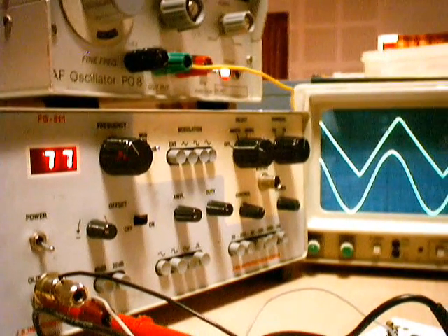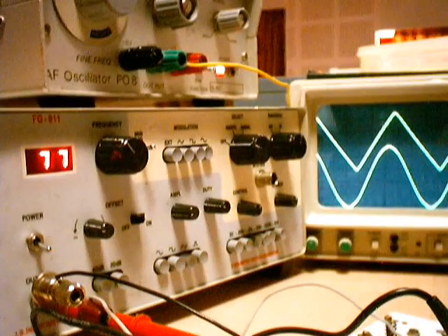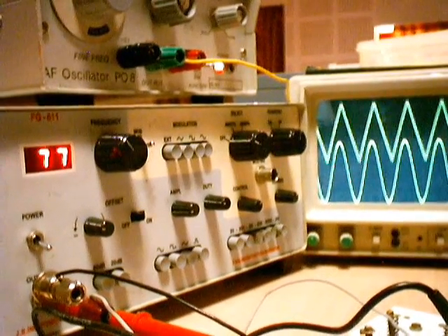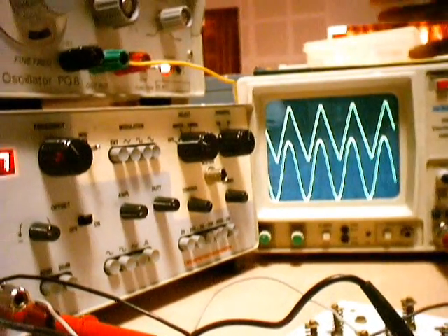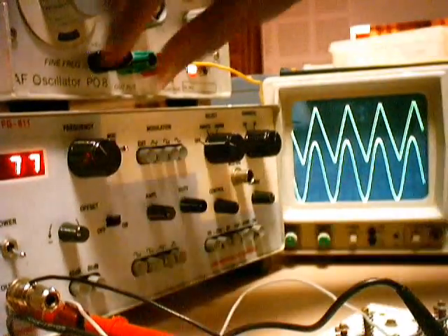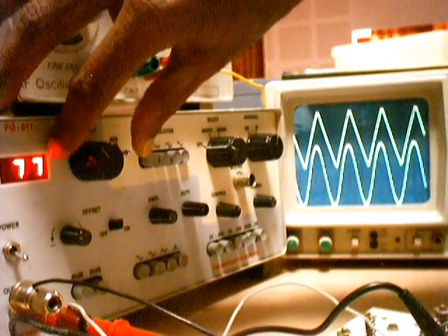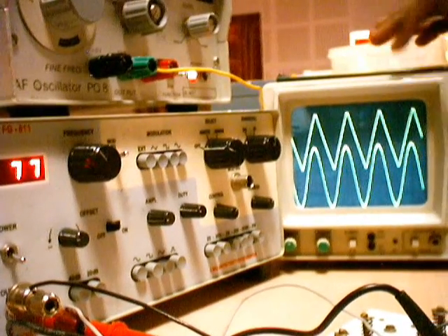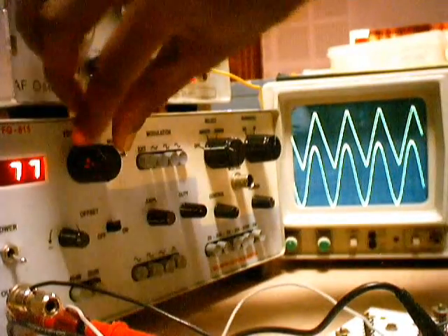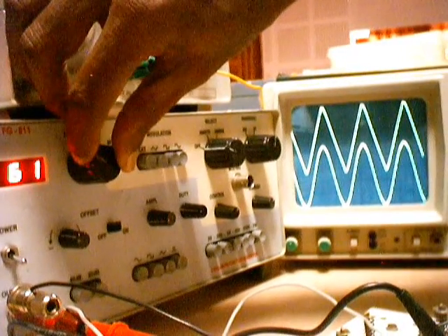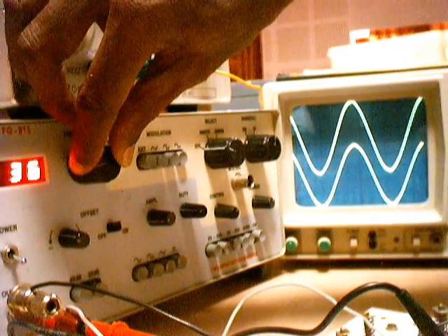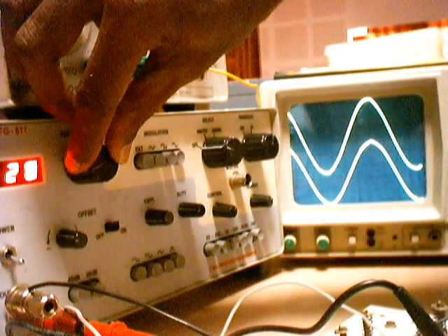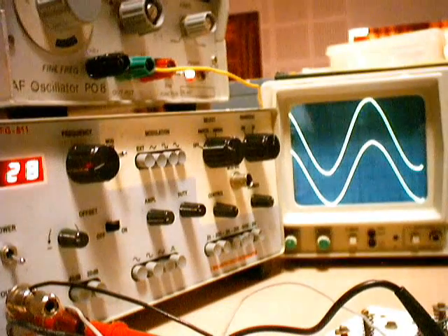Now this is not because of the filter, it is not because of the RC of the filter, it is because of the op amp. The op amp has some slew rate, which is not infinite. So we cannot take this 77 kilohertz as your passband frequency. You are getting a triangular waveform because of the slew rate problem of the op amp. So reduce the frequency such that there is no slew rate effect happening. Even at around 31 or 28 kilohertz, I'm not having any such problem.